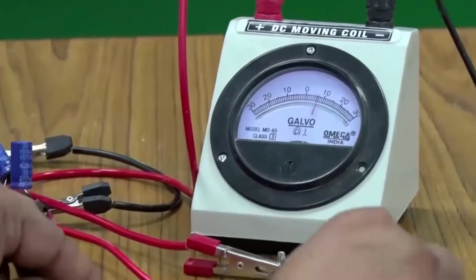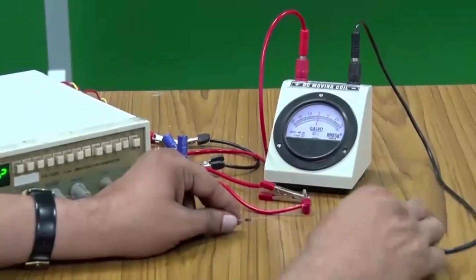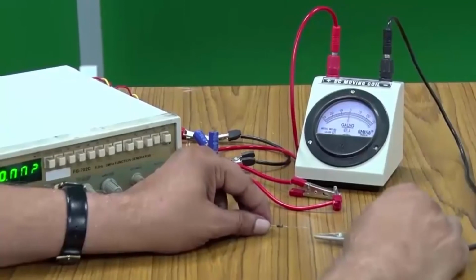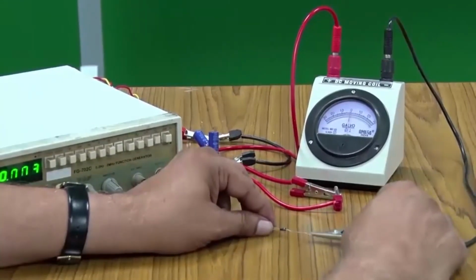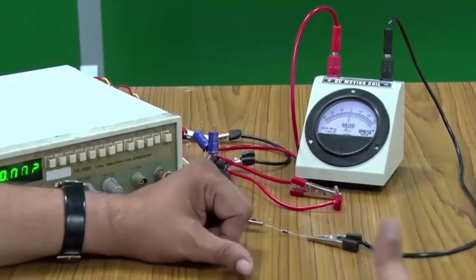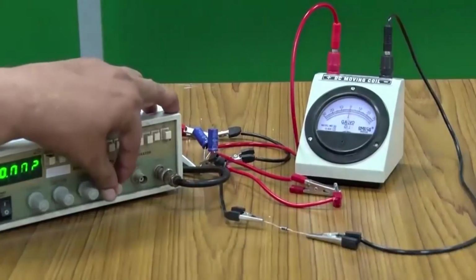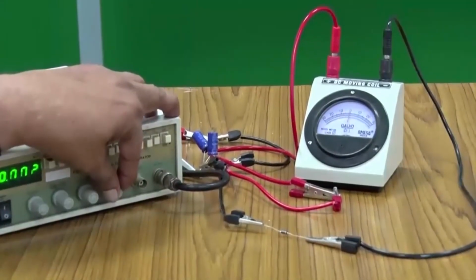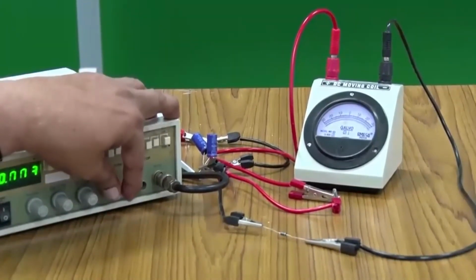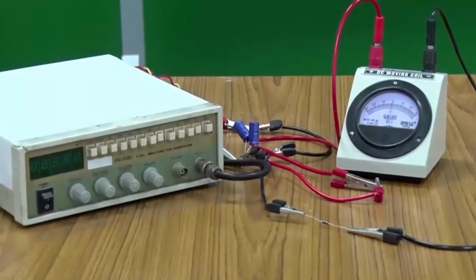So, that shows that this assumption that we had taken, that just forward bias and you have large current, is not true. You have to supply some initial voltage, after which the exponential part of the IV characteristic starts, only then it works. So, let me increase this voltage and you can see that yes, now it has started going. All right. So, we will stop today's lecture here.